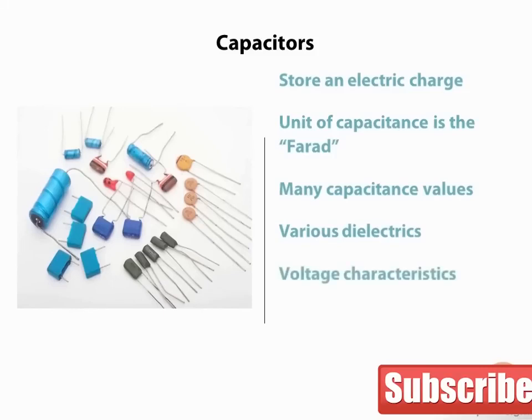Just as resistors have to be selected with adequate power ratings for the application, so must a capacitor be selected with adequate voltage rating. You need to be aware of the maximum voltage that the capacitor may see in the circuit and select a capacitor that is rated above this voltage, and with an ample safety factor. Selecting a capacitor with too low a voltage rating will destroy it, and sometimes with great fanfare, which can be dangerous. Capacitors can have fixed or variable values.